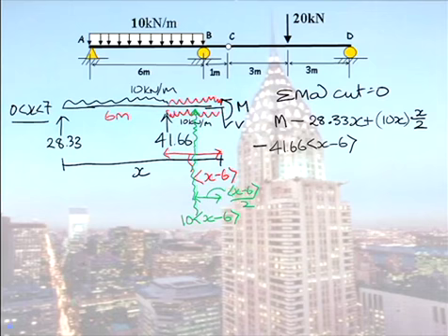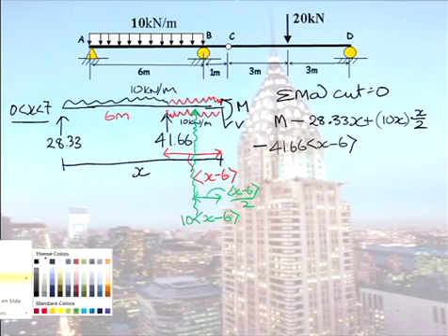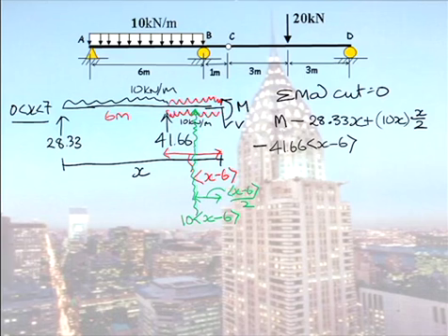So again, I'm just using forces times distances, forces times distances. So in my equation now, if I look at the load, it's going clockwise, so it would be minus 10 times x minus 6. And as I mentioned to you last week, whenever you have a number times a distance like that, you can just automatically square it and divide it by 2, because we always multiply it by a distance that is half of the distance in the loading. Now, all of that equals 0.